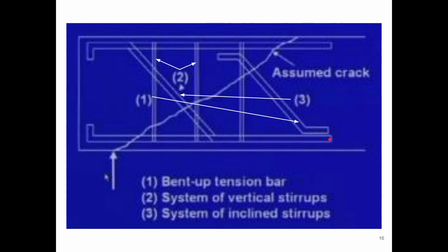Okay, so you can place the bent up bars so that the portions which act in tension have the necessary reinforcements. That is the use of the bent up tension bar. It will take tension at those places. Apart from the doubly reinforcement, you can also provide bent up rebars to provide tensile reinforcements at the required portions.